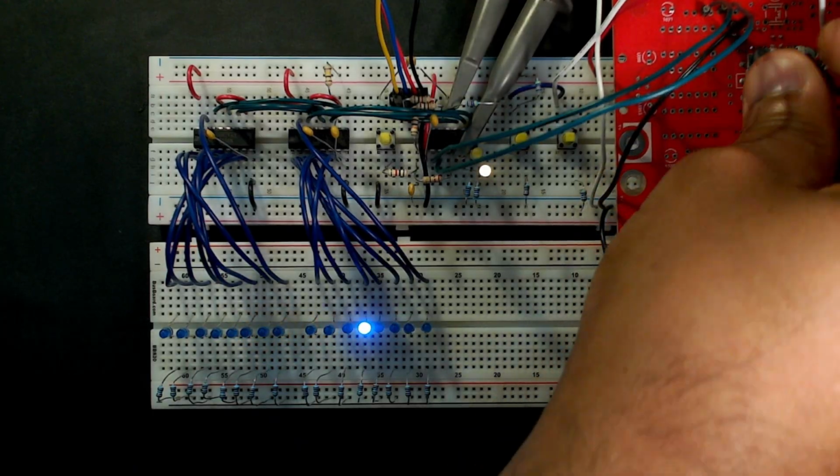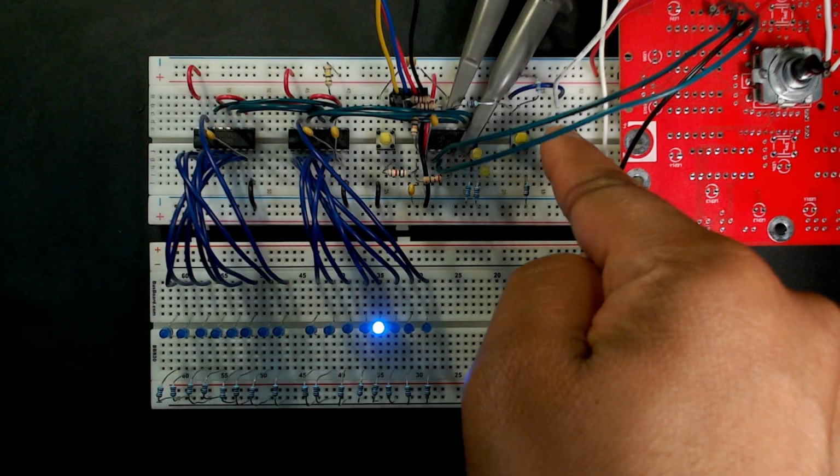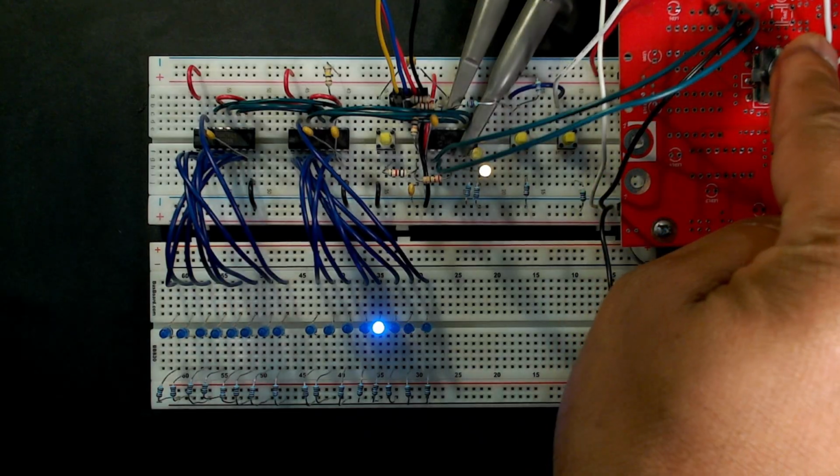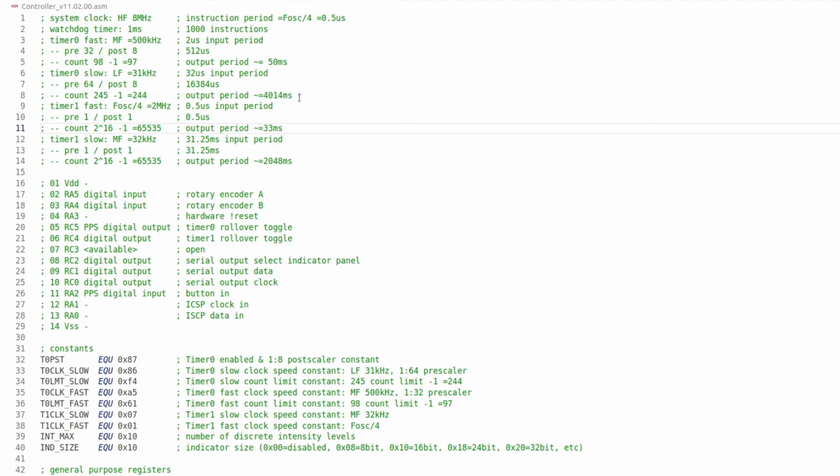And now finally we can focus on the topic that this entire episode was about, smoothing out those abrupt intensity changes. And by now, hopefully you've picked up on why we wanted to do that little tangent to begin with. These abrupt intensity changes require timing to smooth them out. And we just configured a bunch of system states and utilized timer 0 to move between those system states. And we defined 2 different speeds in our timer 0 delay. One we've used already, the 4 seconds. And the other one, well, we're going to use that now.